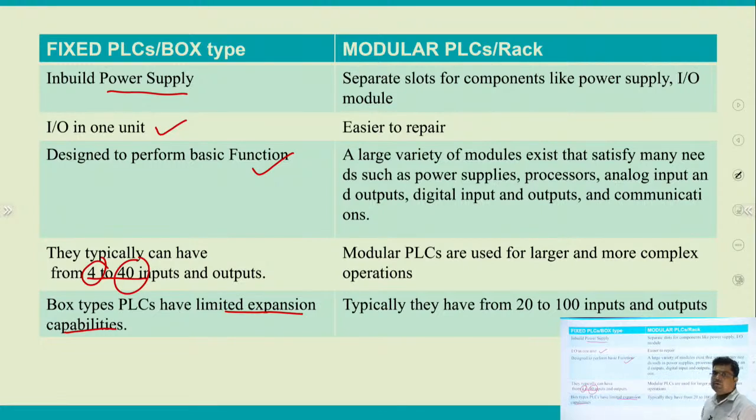Coming to the modular PLC or rack type PLC, which is used for industrial purposes, it uses separate slots for components like the power supply and input output modules.